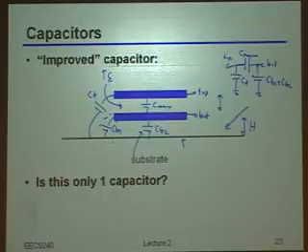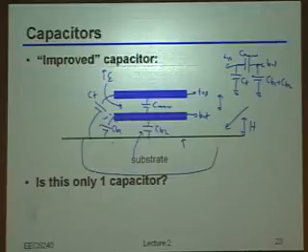So what do you typically build inside of the substrate? N-well. So indeed, let's put an N-well here. What can I do with that N-well now? Is there any clever trick I can play? Why is it useful to have an N-well? You can tie that to a main cap. I think what you said is probably correct. We'll come back to it. Go ahead, Seth. You can control the voltage so that if you keep it the same as the bottom plate, you get rid of that parasitic.